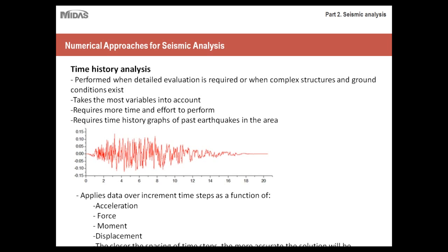analysis that's done in California, Washington, Alaska, Hawaii. Most engineers that I'm acquainted with there typically deal in time history analysis for almost all of their projects, just because of the high seismic region that they're in, and also for larger scale projects that are built there. Time history analysis is their only realistic way to design for the seismic loading that takes place there. So it takes the most variables into account.